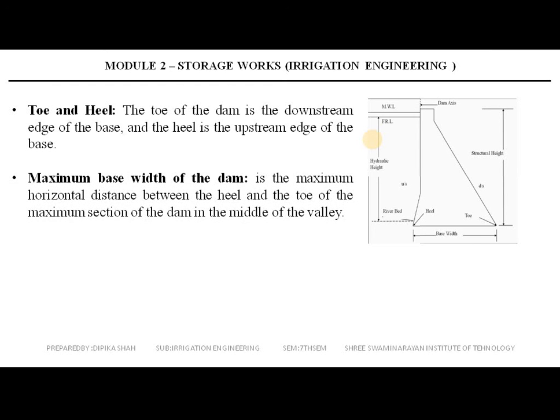नेक्स्ट है मैक्सिमम बेस विड्थ ऑफ द डैम. So the maximum base width of the dam is the maximum horizontal distance between the heel and toe of the maximum section of the dam in the middle of the valley, right?